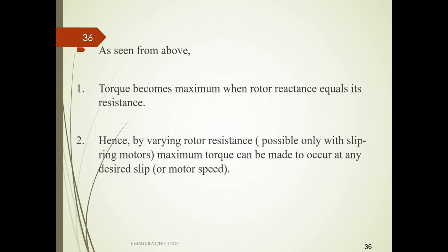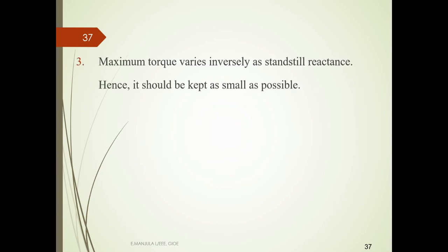So this is only possible in the slip ring induction motor. By varying the rotor resistance we can get the maximum torque at a required slip.